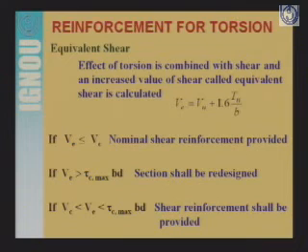The second case is when the equivalent shear Ve is more than tau c max into bd, that is, maximum shear stress into the effective area.